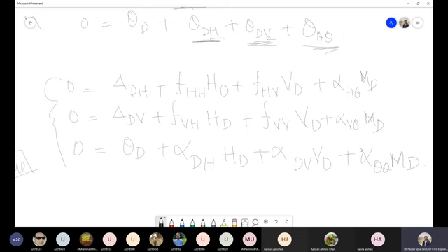Now in these equations you have how many unknowns? First we need to find these three reactions, right? These are the basic unknowns. So we have these three unknowns that we need to find out by solving these three equations. But to find these three unknowns, we need to have these 3, 6, 9, and 12 deflections. Then we can find these three unknowns.